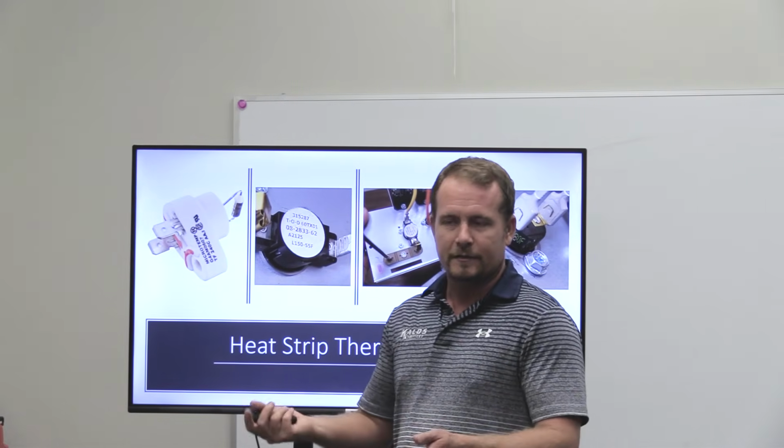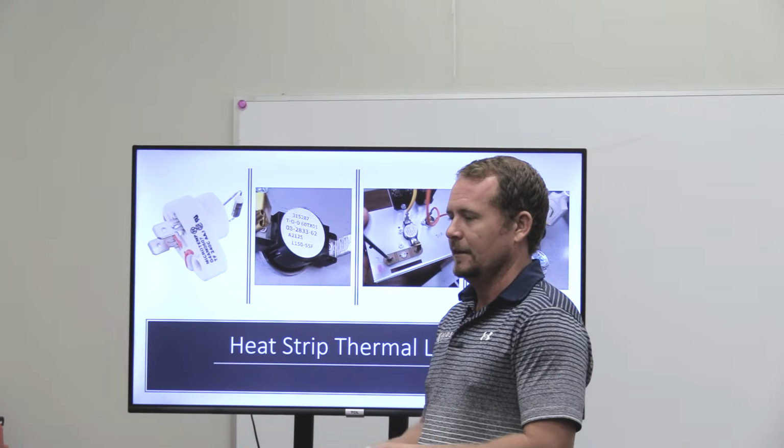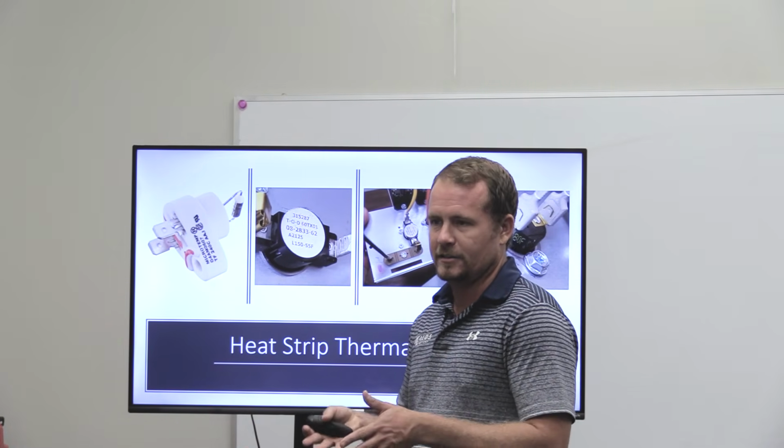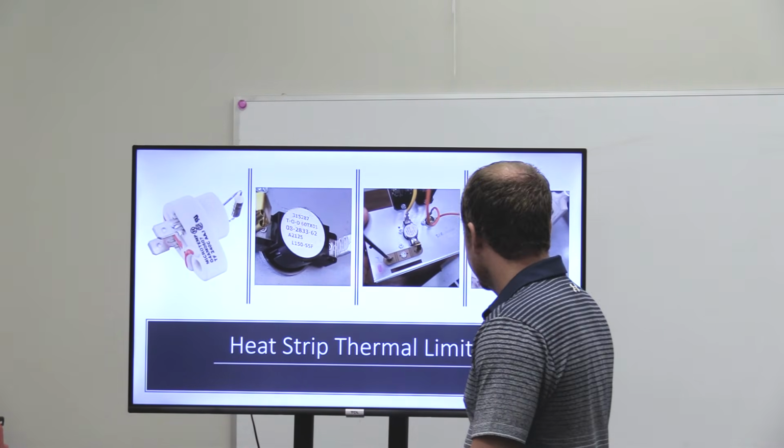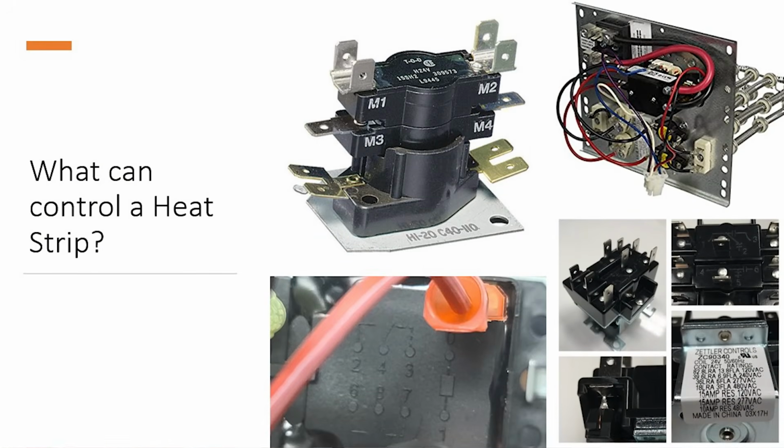Or 0.1 or something like that. Well, look, it's reading 0.1. Is that good or bad? Low ohms means good path. Infinite ohms means bad path. Infinite ohms means open. Low ohms means closed, right? All these are switches. So they don't consume energy. They just open and close in order to protect the circuit.